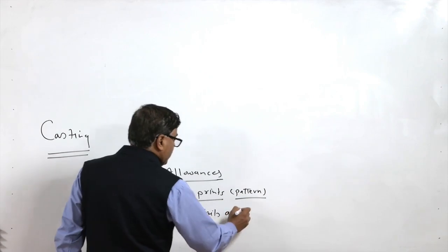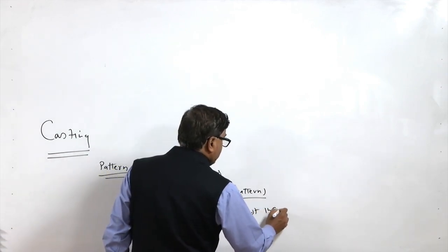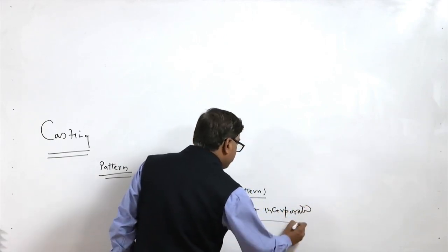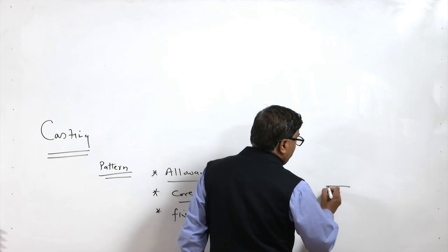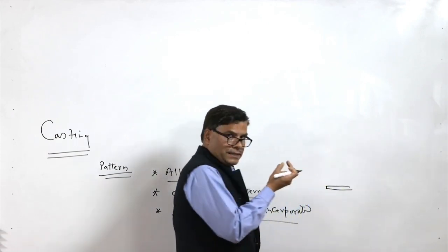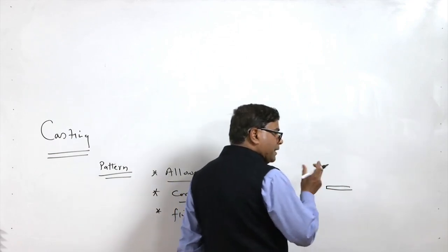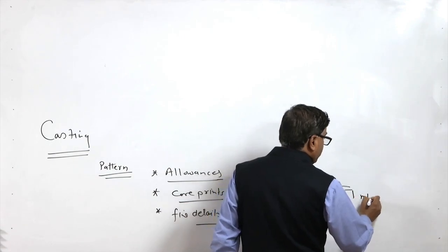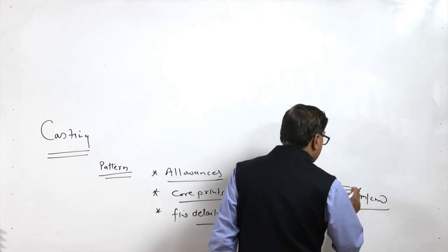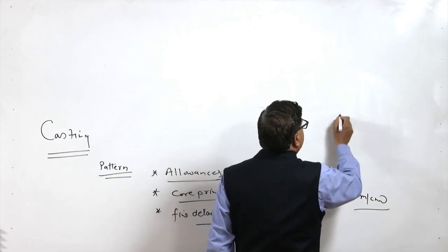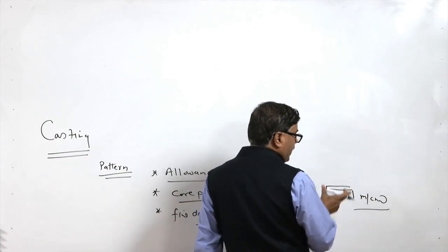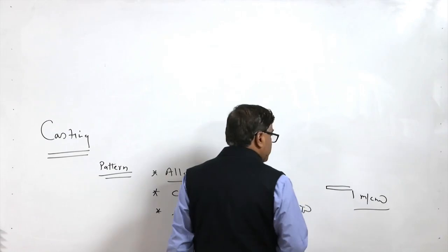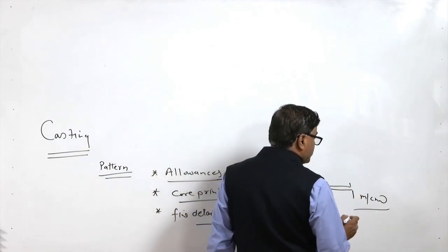And some of the fine details are not incorporated in the pattern, because if the details are very fine, like a half mm thin section of greater length is to be produced, then probably it will be better to machine it out. Or if some slot of half mm thickness is to be made of greater length, means a high aspect ratio slot, then this will be omitted from the pattern, and better it will be made using a machining process.